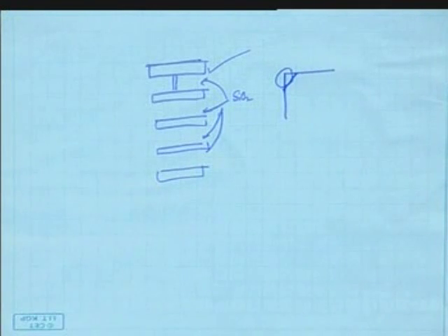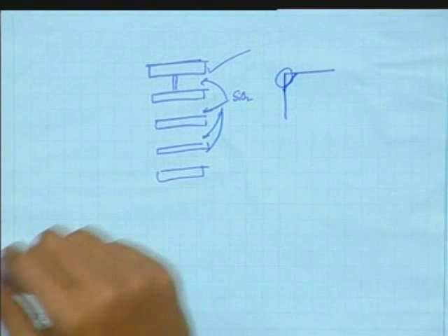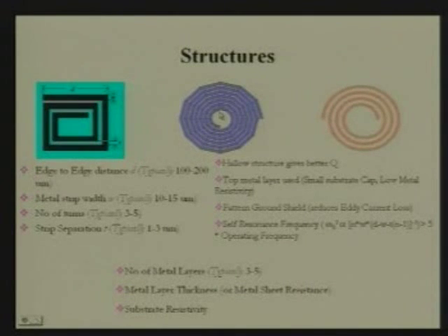See, for example, this is the square inductor, and this, go to the slides, is the polygonal inductor. We have wound it out in the shape of a polygon. Ideally we would have a circular inductor, which would have the highest magnetic flux density and the highest inductance. However, getting an exact circle is also impossible. So we stick with polygonal structures, and these are the typical dimensions.